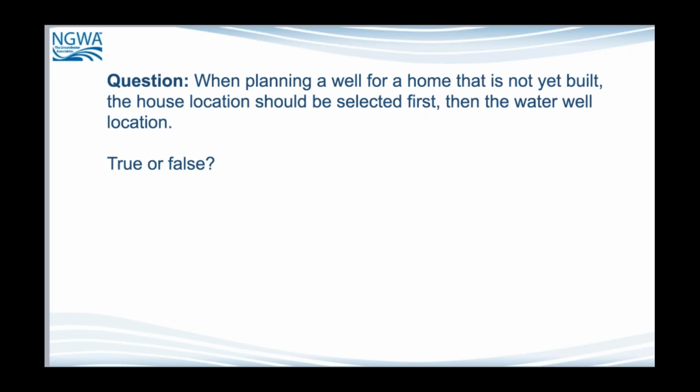So that means that you cannot put it underneath your driveway, and you cannot put it in your garage, and you cannot put it in all these other places where you think that it would be a nice place to hide the well and get away from having to deal with it, or be able to build over the top of it. I've seen a lot of people try to put decks over them and things like that. As long as it's still 8 inches above grade, yeah, you can get by with doing that. But at some point, and we're going to talk about this later on, you're going to have to work on it.